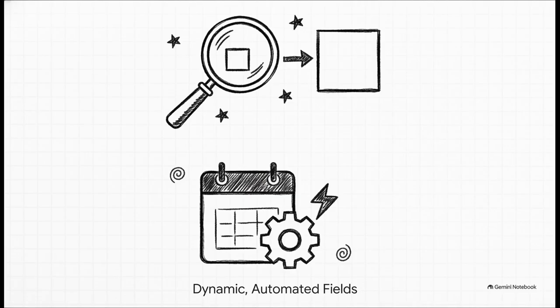And to push your efficiency even further, we've got fields. Honestly, instead of manually typing out today's date or specific drawing properties and then dealing with the inevitable headache of trying to remember to update them later, just type the field command. It lets you insert dynamic data that updates automatically whenever the drawing changes. It is a real game changer.